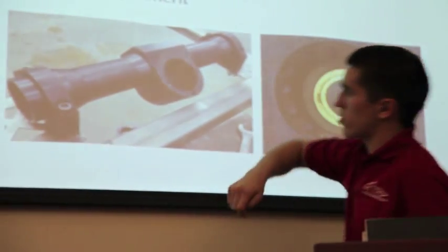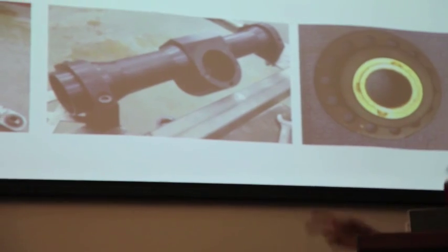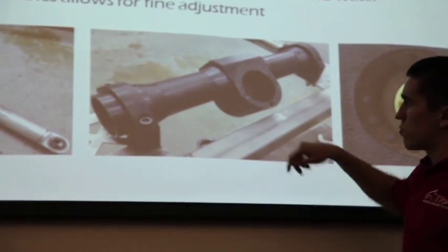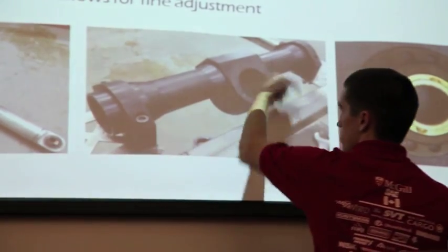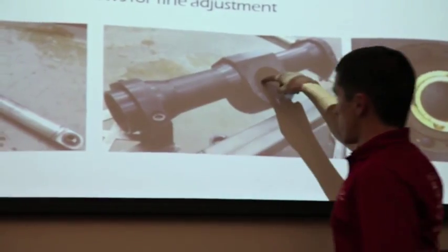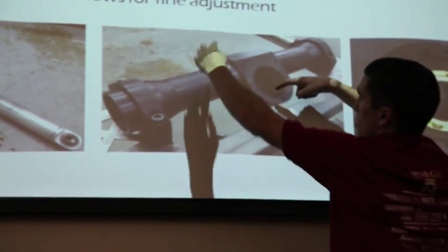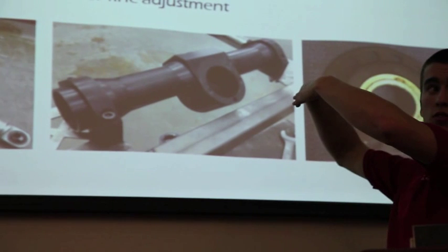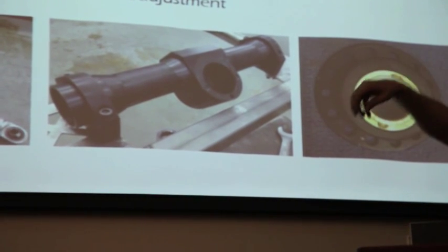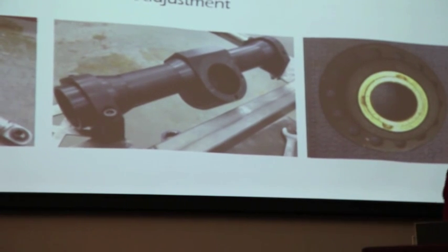Questions? Have we ever tested how tired the drivers can get to try to decide their steering ratio? We did not test that on track, however, we experienced a moment where, behind here, we don't see it in the picture, there's a set screw that is a sort of safety thing. This rack goes into here and the pinion goes into that interface. The set screw on the other side prevents the rack from deflecting too much, and we had this set screw too tight, so it was putting pressure on the rack and a lot of friction was generated.